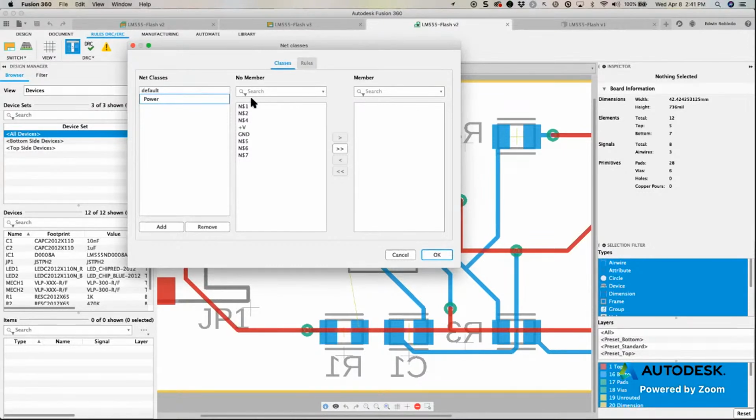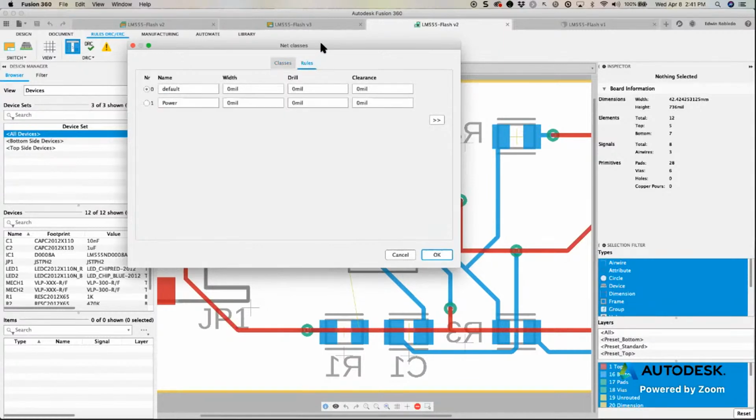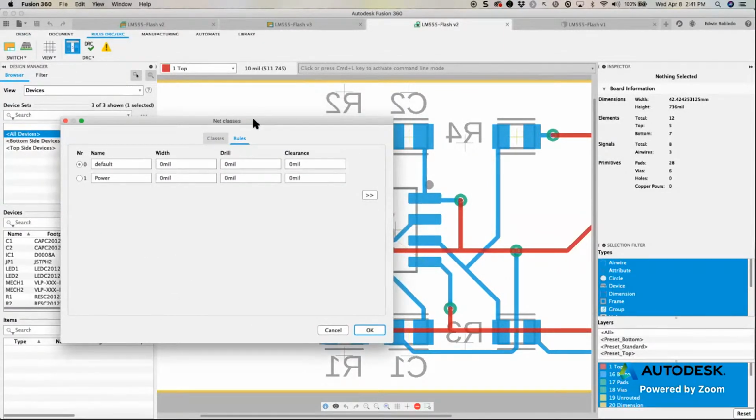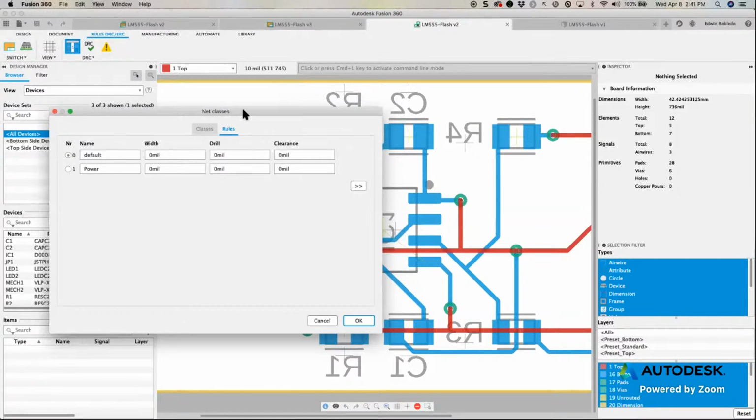Yeah, kind of a key thing while Ed's writing this out. The key thing to remember with everything in the DRC is that you're setting a minimum. So it's okay to be larger than that, whatever that value is, but what you're really defining is a minimum. So if you need it to be smaller than that, that's where you're going to run into difficulty. So the key is whenever you set in the DRC, that's the minimum baseline. From there, everything else can be bigger.